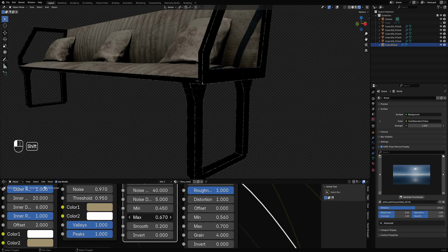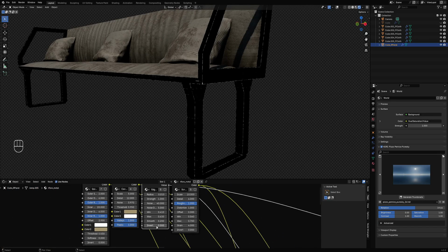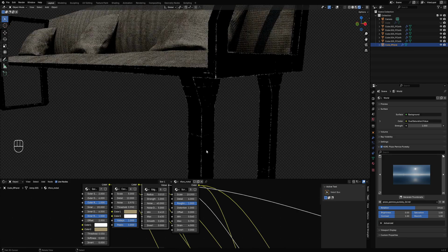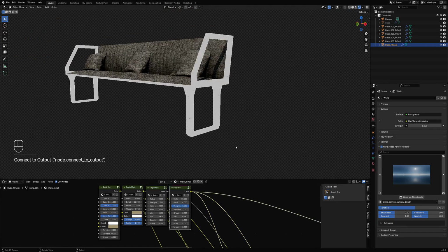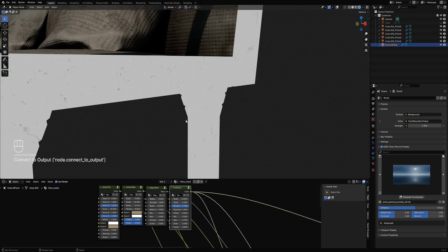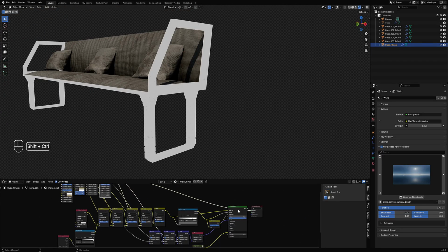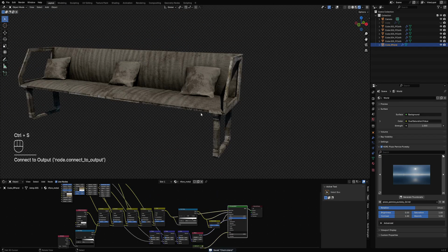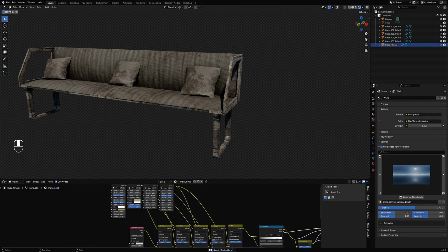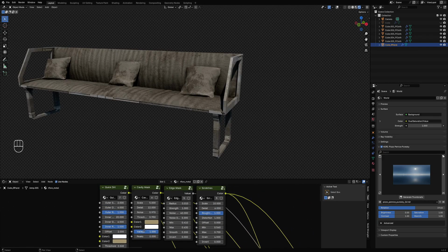The scale of the noise determines the breakage in the texture using the min-max values. Here we go. You can invert this or smooth the resulting texture. Okay, and the scratches, I guess they're at the right size. There you go, as dirty as the cloth. So all we need to do is add the peaks in the cavity mask. There.